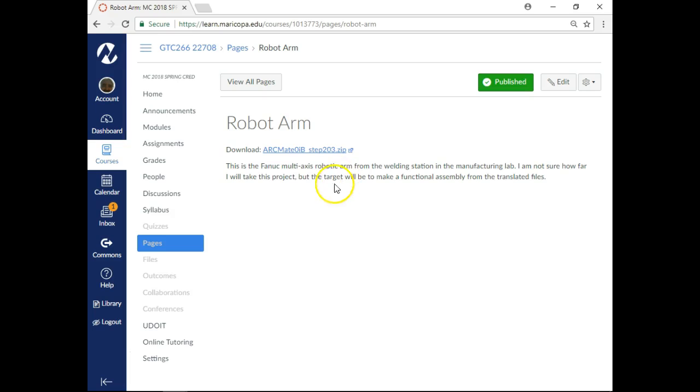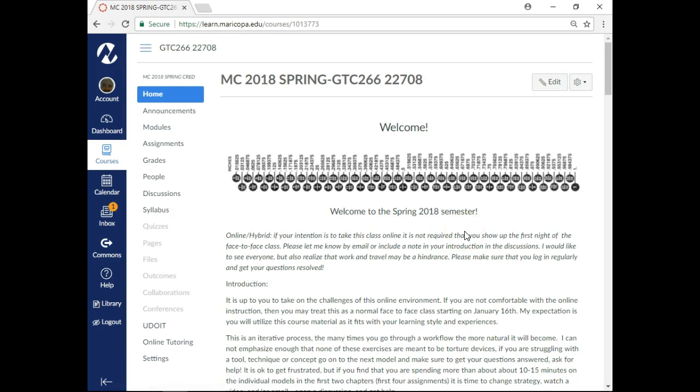I have that zip, and when you bring a converted file into the assembly, it's not going to have mates. Everything may be in position, and I need to grab a snapshot of it and put it up there for a little more information, but it doesn't work. If you go to move something, you just kind of throw it out into space, and it's not doing what was intended.